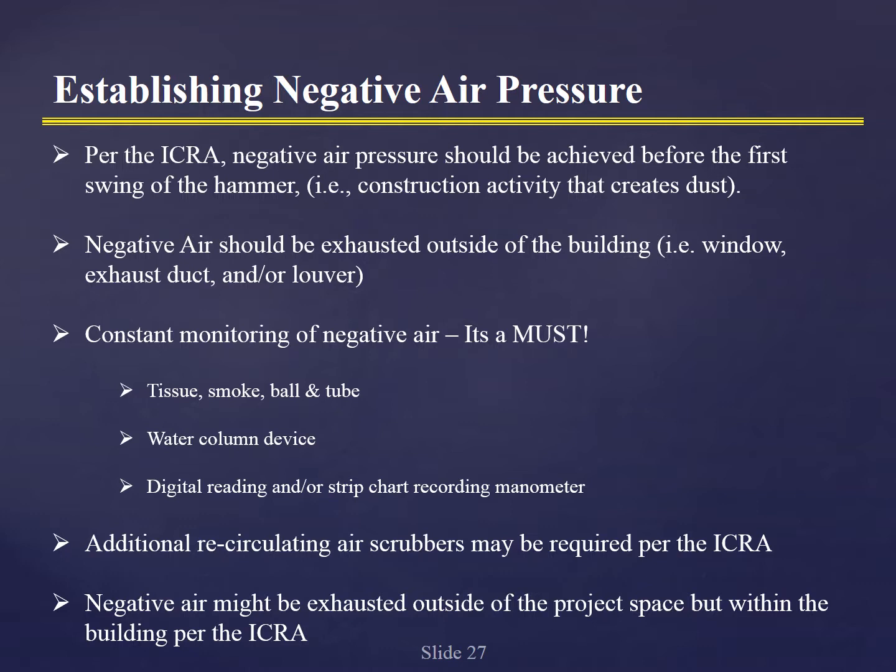I know there's lots of discussion, and there is code that allows us to use HEPA filters and recirculate in the building. But you must be very careful. There's a visual negative connotation to when we do that, so be very, very careful. Some people have suggested pushing it into a plenum so as not to make it an eyesight issue. Again, constant air monitoring is a must.